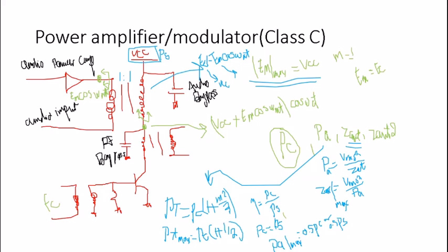So what we get right here is that the maximum peak voltage that we can find at the output of this transformer is only VCC. So given that, we can calculate the output impedance for this audio amplifier, which will equal VCC, obviously as an RMS value, you need to square root, all squared, divided by the power of that amplifier.